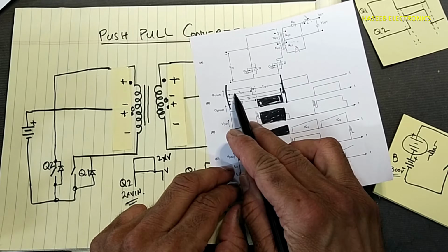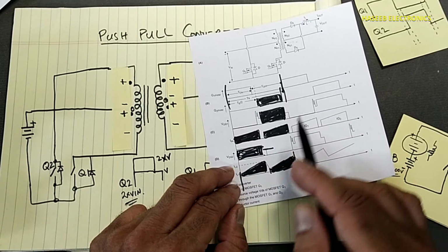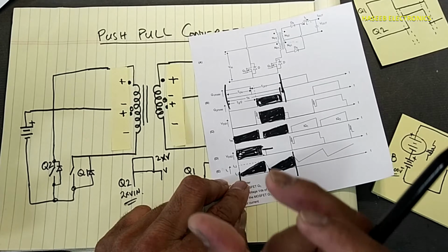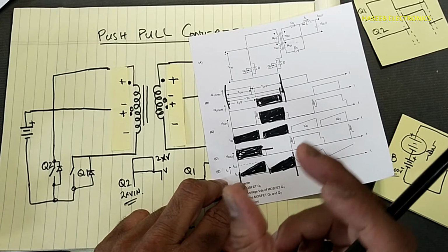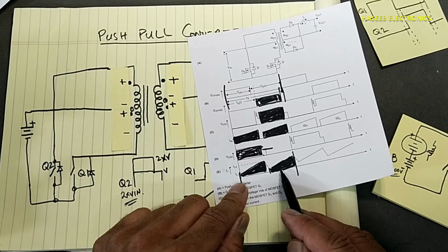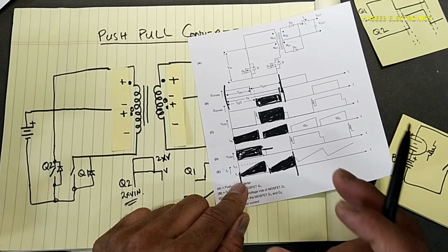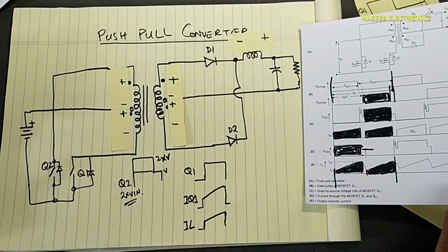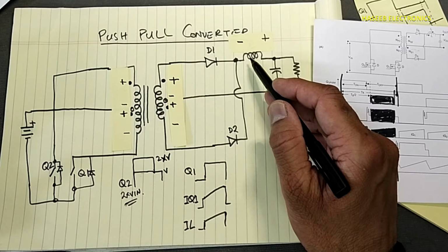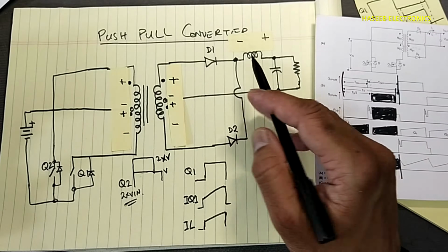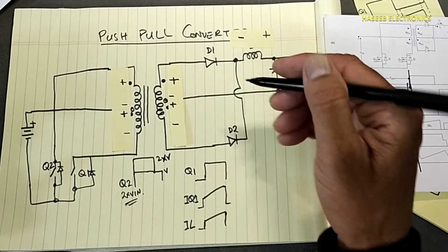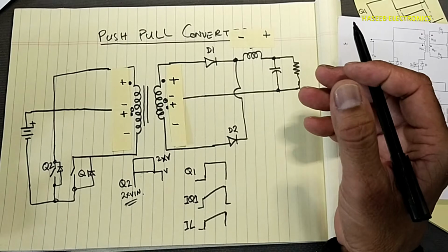After each switching half cycle, there is dead time. It will cause two pulses to be produced in one switching cycle, which is the composition of two halves. The inductor will receive two pulses. When we have high frequency, the ripple voltage is decreased. So this is the benefit of this topology, that it provides low ripple in the output.